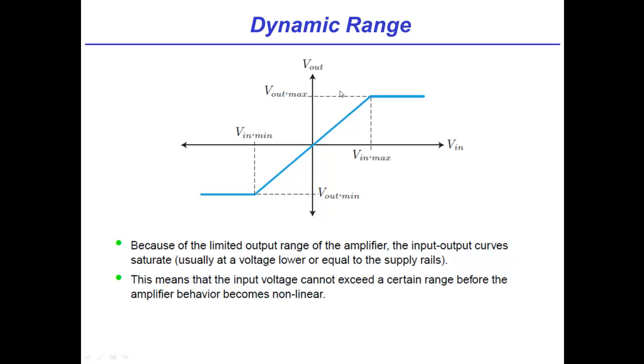Hey, so that must have been what we were talking about earlier about linearization. So we're treating this amplifier as a linear circuit according to the circuits we just did a slide ago, but that's only true in a certain region, right? Obviously, beyond Vout max and below Vout min, it doesn't really work. It's not really a linear device. That's right. So all those nice current and voltage-dependent voltage sources and resistors that we use, those only work to model this as an equivalent circuit in here. Makes sense. Okay. Not at the edges.